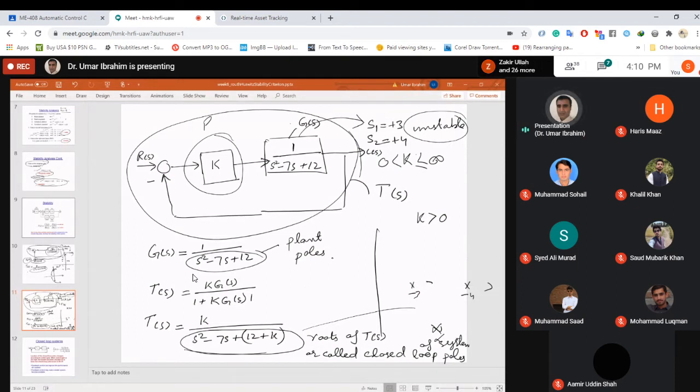How do I know that? I know because I know root locus. You will know that too once you study root locus. So I do not need to do any calculation. I know that initially they will move towards each other. And at a certain point, they will collide with each other. Once they collide, one of them will move upward and the other one will move downward, at 90 degrees.